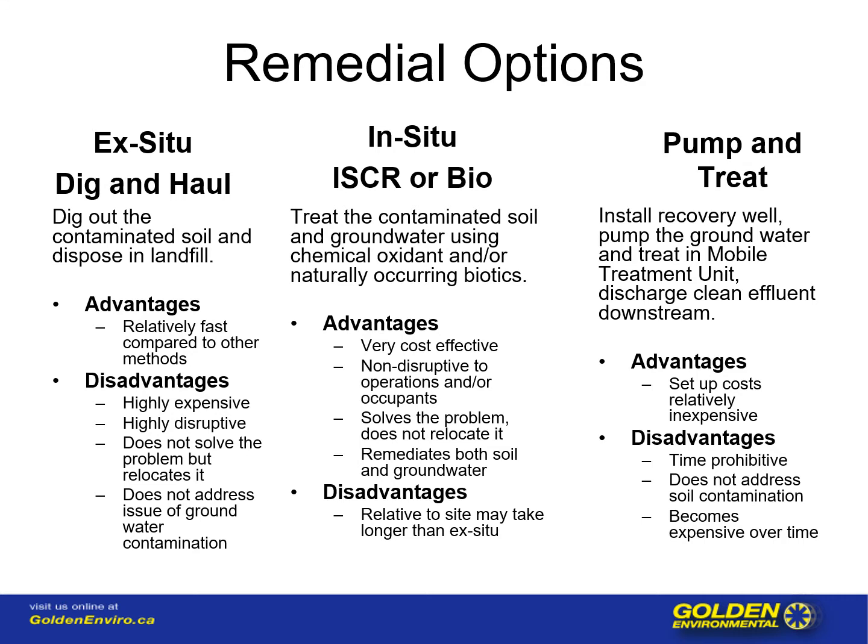The majority of microbes with hydrocarbons are aerobic microbes. There are some chlorinated ethylene microbes which are anaerobic, and special conditions need to be created in order to ensure that oxygen does not reach those microbes when remediating such contaminants. However, the majority of microbes are aerobic microbes that digest contamination.